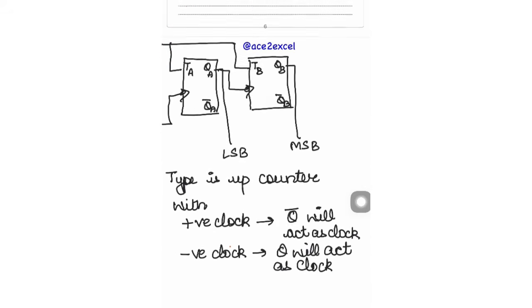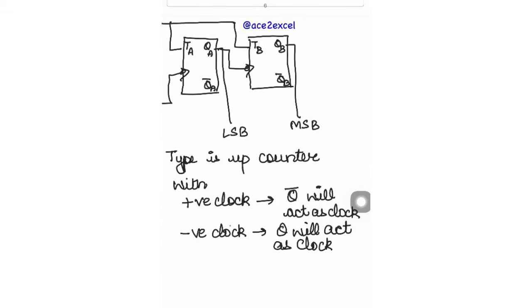Now, always keep in mind another fundamental concept, that outermost flip-flop is the MSB and innermost flip-flop is the LSB. Right. Now, we are using negative clock, so Q will act as the clock pulse for upcoming flip-flop circuit.